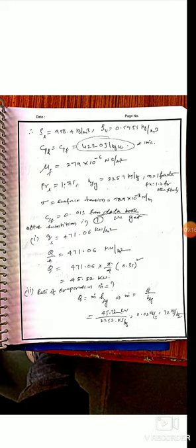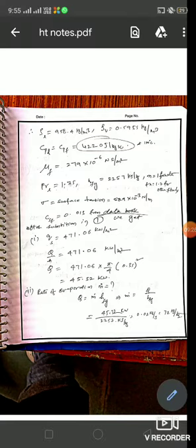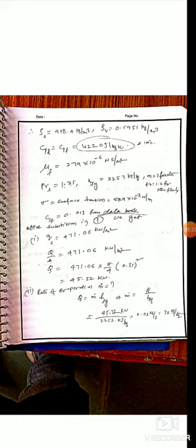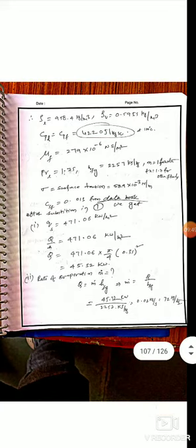Now the important thing we need to remember is also that N is equal to 1 for water, and N is 1.7 for other fluids. It is a given, already pre-existing thing. Experimentally they have calculated it. It's a type of dimensional analysis. And sigma, which is surface tension, again you need to take at 100 degrees Celsius. And like specific heats, we need to take everything from the data book.